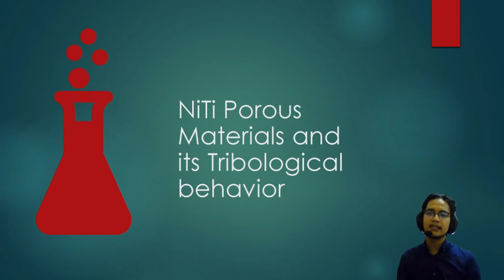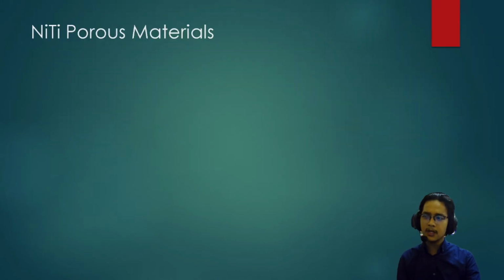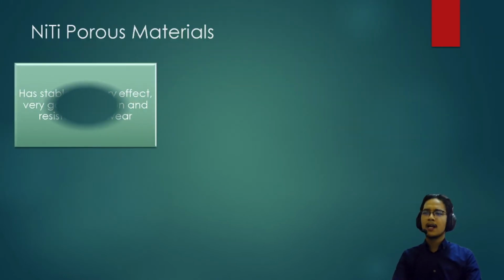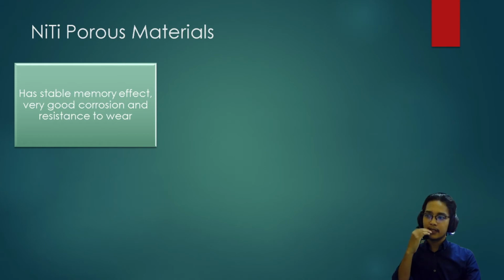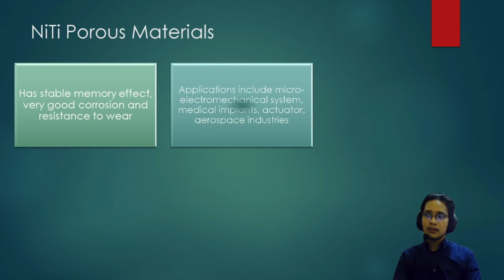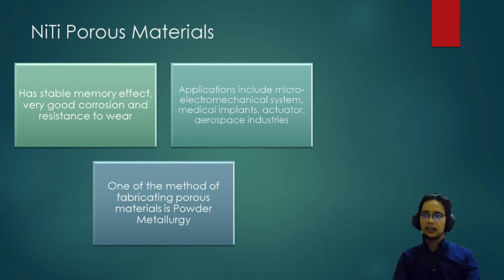Next, nickel titanium porous materials and their tribological behavior. Nickel titanium has a stable memory effect, very good corrosion and wear resistance. Nickel titanium porous materials have many applications, including micro electromechanical systems, medical implants, actuators, and aerospace industries. One of the methods of fabricating porous materials is powder metallurgy.